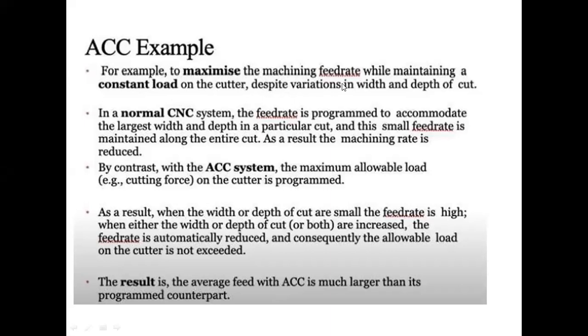Okay, you see, we maintain a constant load on the cutter despite variations in width and depth of cut. At different points of time, you will have different width and depth of cut, depending on the part geometry. So the load will change on the cutter, because it is not contacting the same geometry all the time. The contact surface is not the same, so the width and depth of cut will change, and therefore the cutter load will change. So we are trying to ensure that a constant load is maintained. Why? Because we want to maximize the feed rate.